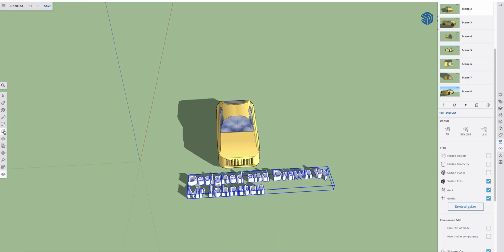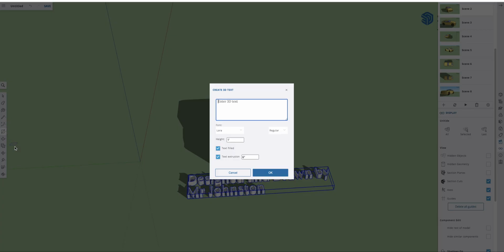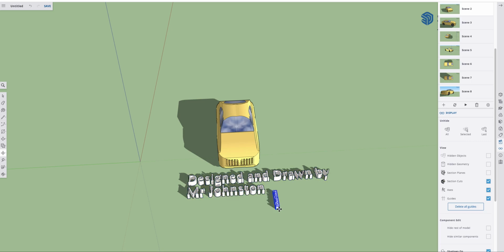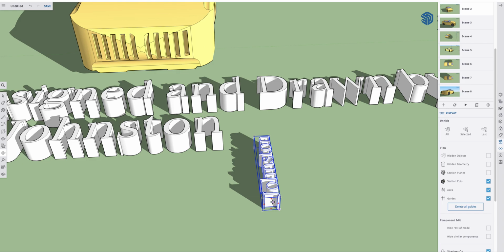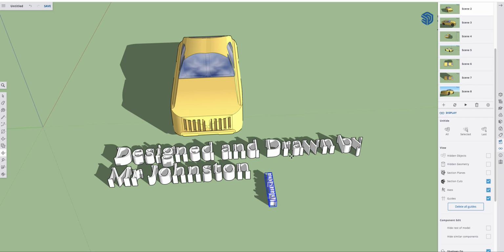All right. So I'm actually going to go back to the lettering and see what I used here. It was 6 inches extrusion to 1 foot lettering. That's too big. So I think you guys should put in the lettering. How about like 4 inches? I'm going to try that. I'm just going to try it out. Make the height 4. And actually maybe make these 4 and 4. That's going to be better. It's even a little tall, so you could do 4-inch high lettering and maybe make the extrusion like 2 if you want it 3D.